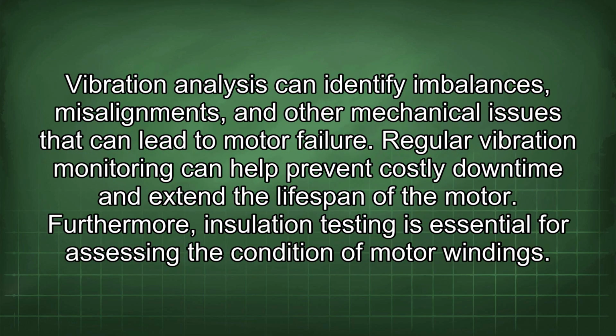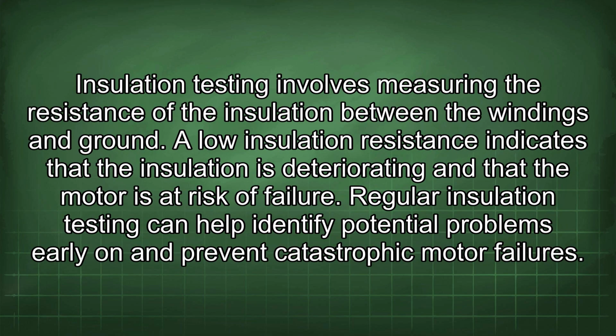Vibration analysis can identify imbalances, misalignments, and other mechanical issues that can lead to motor failure. Regular vibration monitoring can help prevent costly downtime and extend the lifespan of the motor. Furthermore, insulation testing is essential for assessing the condition of motor windings. Insulation testing involves measuring the resistance of the insulation between the windings and ground. A low insulation resistance indicates that the insulation is deteriorating and that the motor is at risk of failure. Regular insulation testing can help identify potential problems early on and prevent catastrophic motor failures.